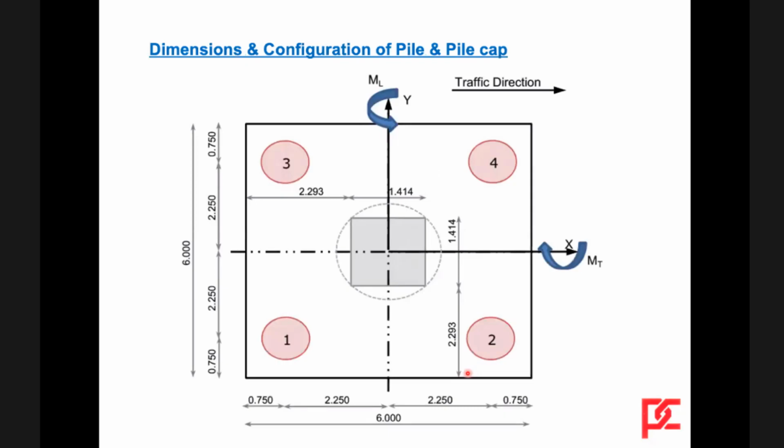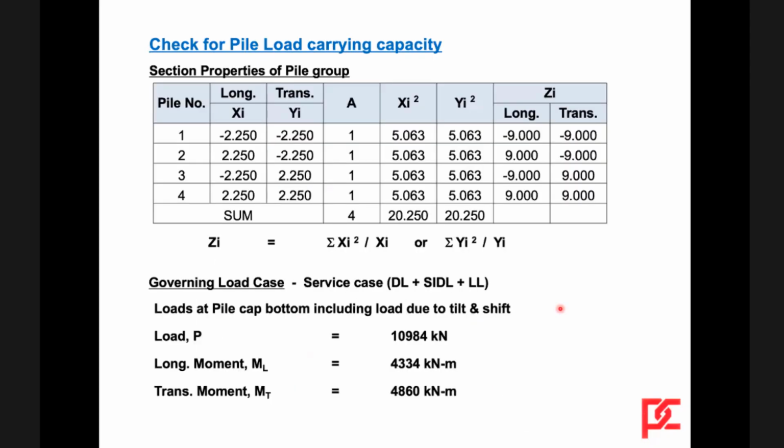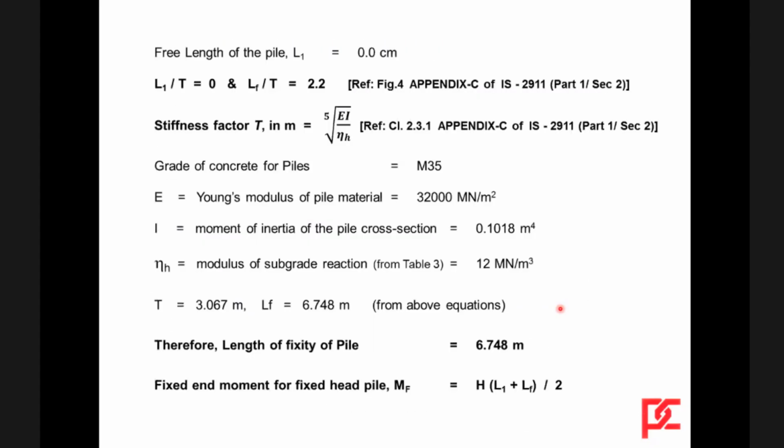the control section is here. We have to check whether this is okay here. That is also all right in our case, where the pile load is only about 400 tons and we have got a 1.8 meter thick cap. It is not critical, but that check also needs to be done, and we have done that.